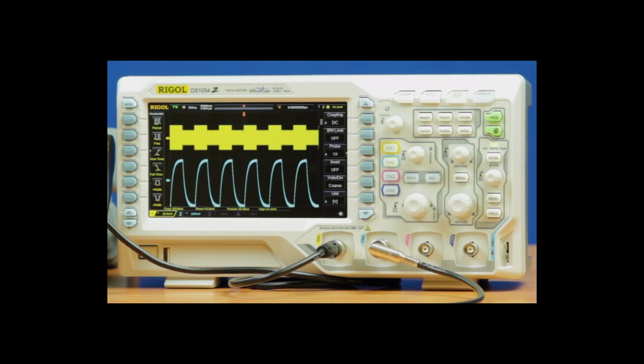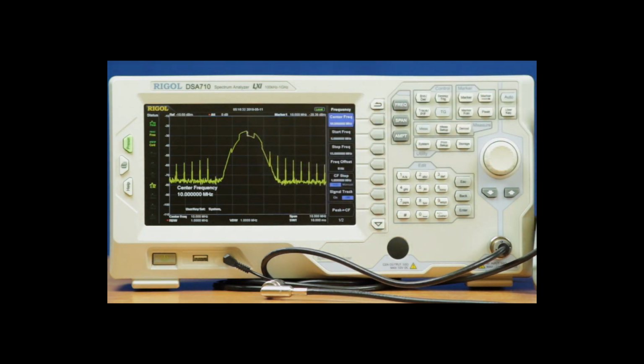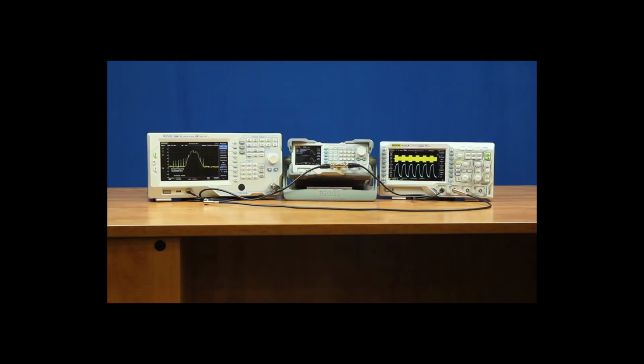So here we have, in the yellow on the top, the carrier, the amplitude modulation. We can see the spans of 500 microseconds each, where it's high and low. And then in the blue, we can see the demodulated zeros and ones coming out of the analyzer that are coordinated perfectly in time. If we looked closely at the spectrum analyzer, we can see the amplitude modulation changes here as they go from periods of high and low within a single sweep. So that creates a little bit of spectral energy, but really is a great way to see both the time and frequency domain view of an amplitude modulated digital signal, in this case an amplitude shift key.